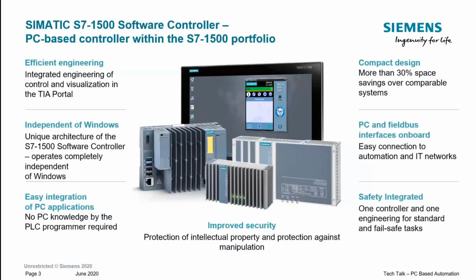So what exactly are we talking about when we're looking at the S7-1500 software controller? What our colleagues in headquarters development have done is they have taken the firmware that runs inside of the hardware, the standard S7-1500 PLC, and it has been ported to be able to run on top of the x86 architecture. So the architecture that runs in a standard Windows desktop computer. So that obviously means the industrial PCs, like you can see on the right-hand side of this graphic.